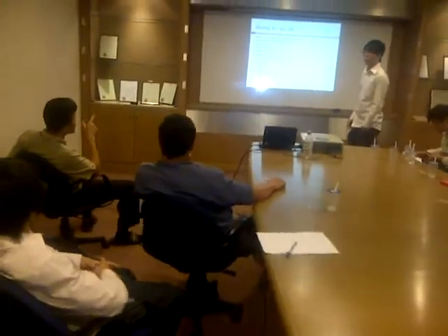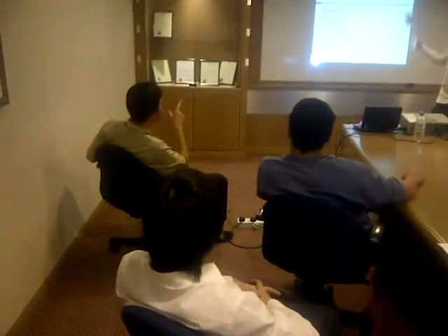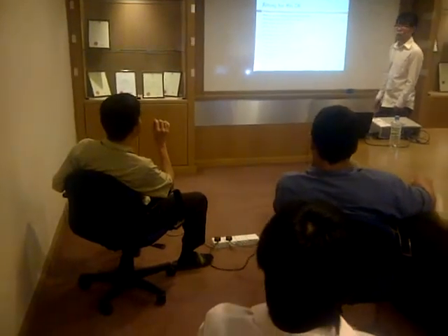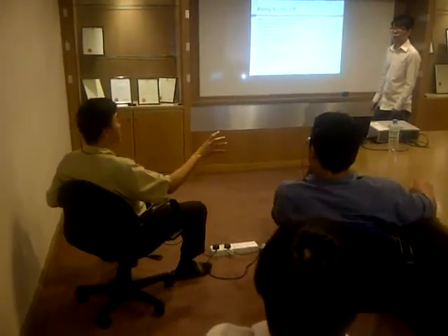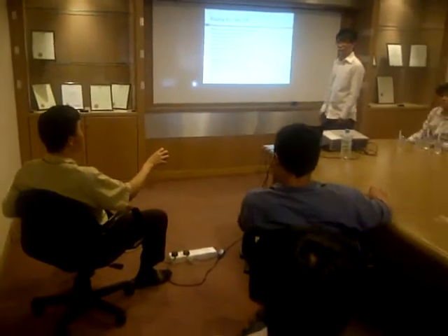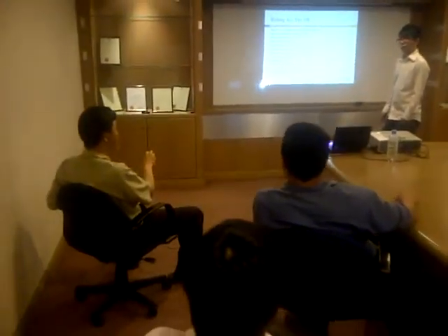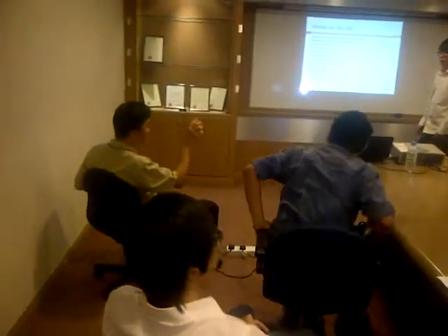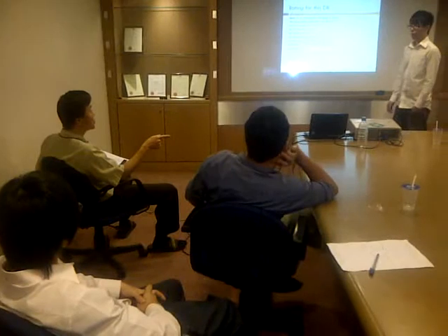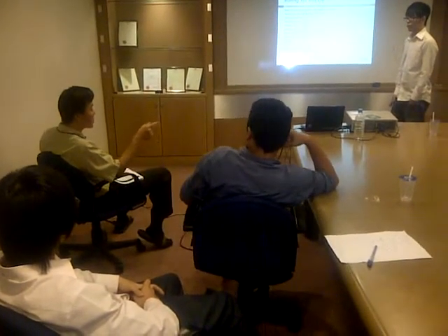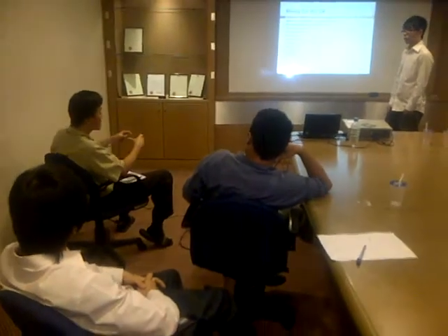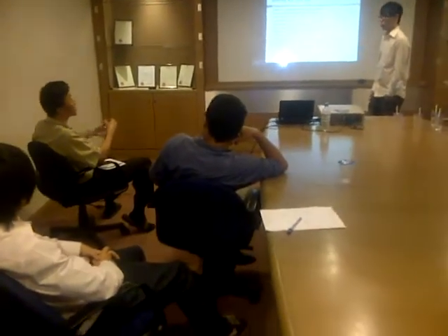I just look at it, 35 mm square may not be enough for the 125 amp. For the 125, you see, in the IEE wiring regulation, it already mentioned very clearly. You size the breaker first. After that, you size the cable based on the maximum current rating of the breaker. Because you have to assume that if the breaker does not trip up to that amp, this cable will actually melt, or short circuit, or cause fire.